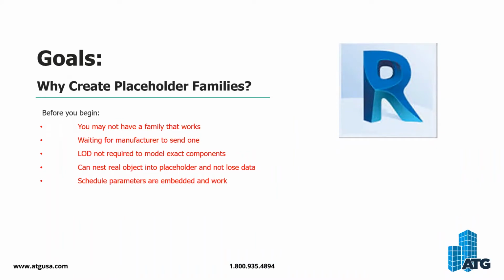You'd be able to, instead of replacing the entire family and type swapping it with the new one that you've gotten from the manufacturer, just nest their 3D geometry into yours that already has all the shared parameters, and skip the step of loading your shared parameters into their file so that it actually does schedule correctly. So that's a nice little component object there.